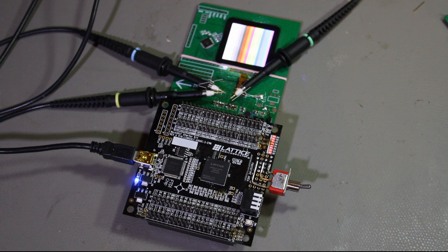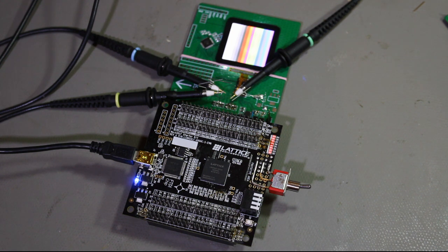In this video, I'll be showing you how I interfaced a MIPI LCD to an FPGA. Specifically, this small LCD from an Apple iPod product, the iPod Nano 6th generation. This is a 1.54 inch LCD, 240 by 240 pixels. I'll be explaining in a little detail what it's going to take to generate MIPI signals using an FPGA.